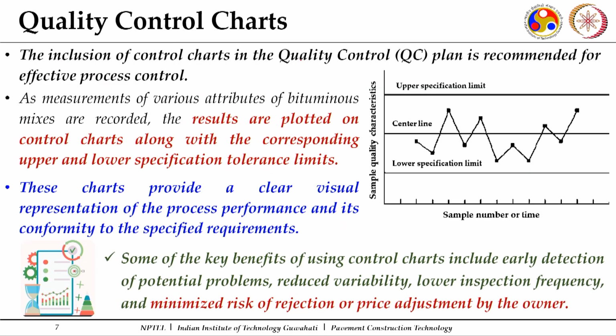The inclusion of control charts in the quality control plan is recommended for effective process control. As I mentioned, effective process control can be done by using these control charts, as measurements of various attributes of bituminous mixes are recorded.